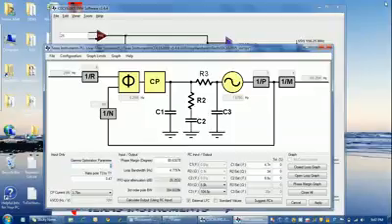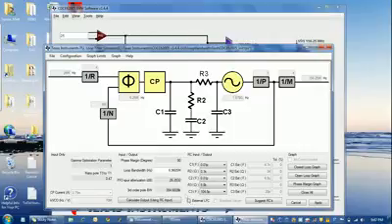When the input reference clock is high jitter and requires jitter cleaning, a low bandwidth is needed. In this situation, the better option is to use external components for the loop filter because larger capacitive values are available. In this example, we'll first generate an internal loop filter.